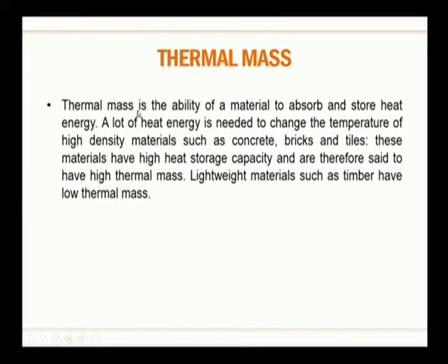Thermal mass. Thermal mass is the ability of a material to absorb and store heat energy. A lot of heat energy is needed to change the temperature of high density materials such as concrete, bricks and tiles. These materials have high heat storage capacity and are therefore said to have high thermal mass. Lightweight materials such as timber have low thermal mass. This is why, when you are looking at buildings for colder climates, thermal mass becomes very crucial, because these are the materials which have high heat storage capacity.